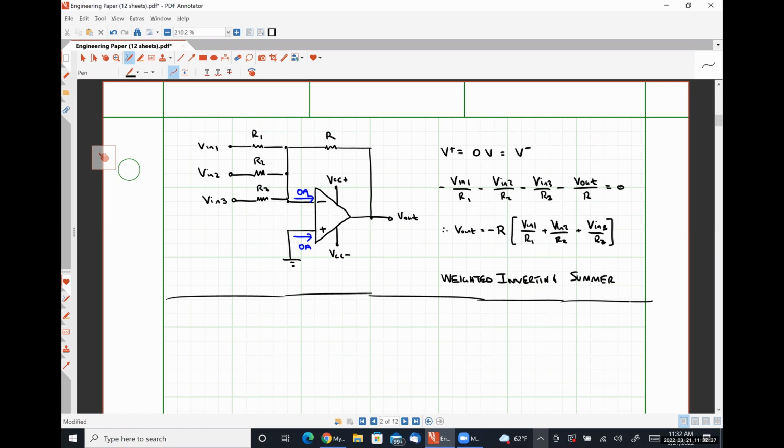The voltage present at our non-inverting input terminal is 0, and the voltage present at our inverting input terminal would be multiple values. The resistor has to be there in order to accommodate having different input values. It also has to be there because we would be applying a very large differential voltage directly to the input terminals.